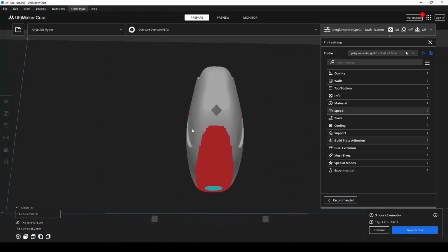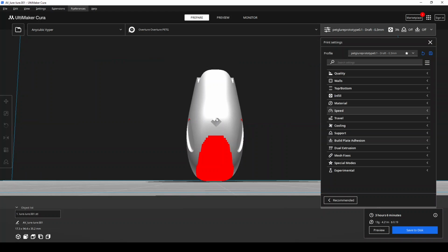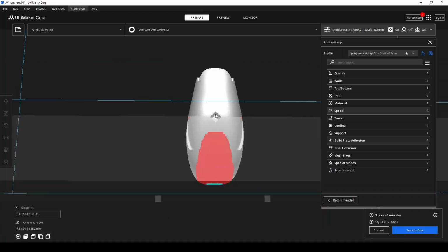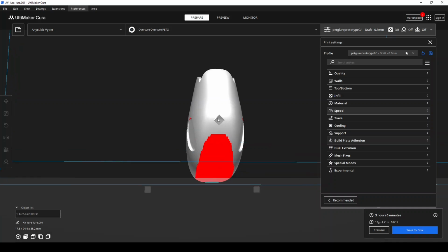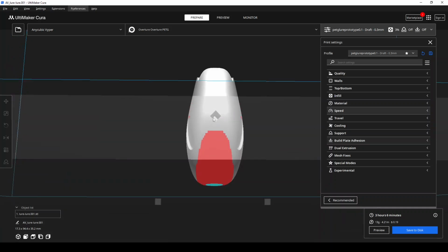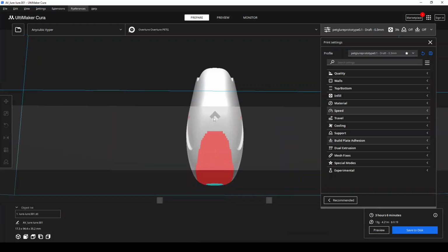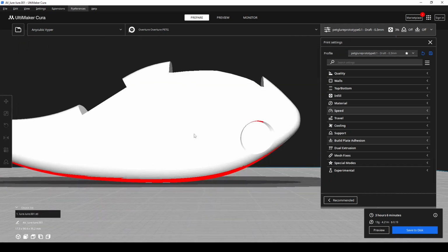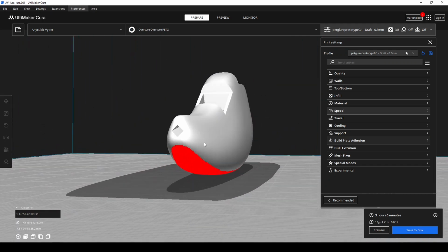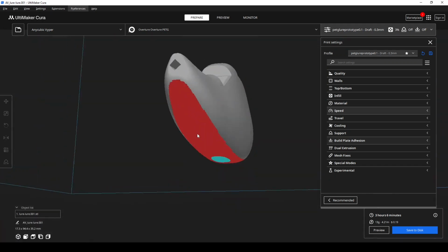It's not a big deal to clean it off. If you'll notice here, if this was a cylinder, it would show red all the way down here, and it would want supports. Obviously, you can put a support blocker there, but you're printing something that the slicer is telling you needs supports to be a cleaner print. That's why I like to use these cubes or diamond shapes for the line ties and hook hangers.